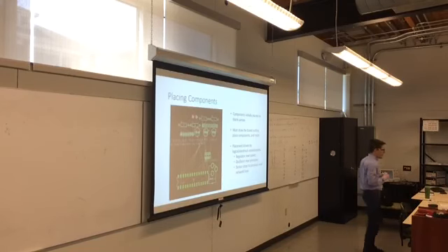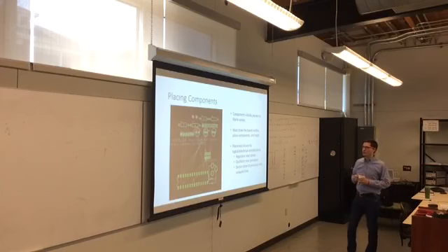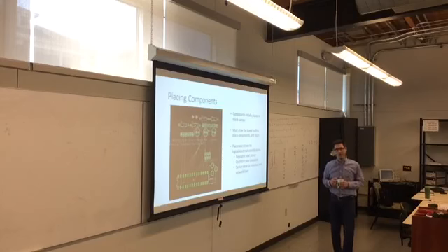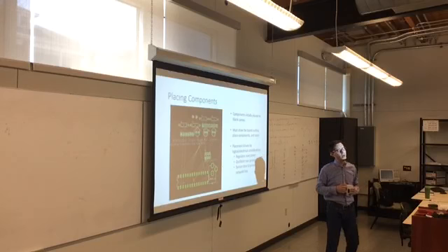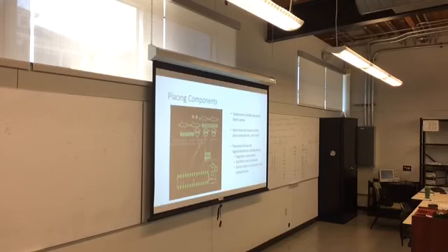There are 100 different heuristics on how to lay out a board. At certain frequency, right angles become antennas, and they become radios, and they radiate, and you get noise. Sometimes you have to put ground planes on your analog components. You don't want your digital and analog devices to be on the same ground plane because they could have crosstalk, they could have ground loops. There's a million different heuristics because this starts to become an analog problem. So I'm an engineer, I like digital things, I don't like analog things. But this truly becomes an analog problem because of all the electrical signal going on here.